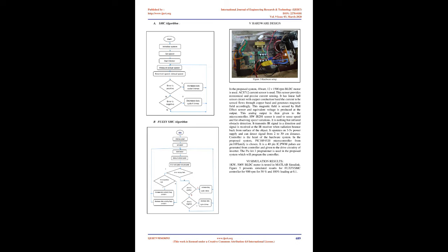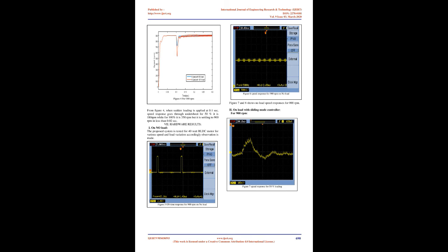Fuzzy logic control is based on linguistic variables, so conversion of physical input to linguistic variables is called fuzzification. 2. Inference. Inference consists of a set of if-then rules which are established for decision-making. Fuzzy rules are nothing but a process for control action. Control action is based on how rules are defined. By proper adjustment of membership function and fuzzy rules, the controller's performance is improved.